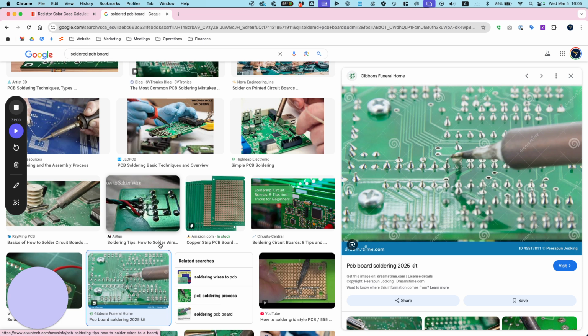Okay, that's good. Oh, I'm missing a little back there. You see that? Okay, so I'm going to just try to reflow it. Not even put any more solder. I'm just going to reflow it, just pressing it. Okay, it's not enough, so I'm going to add a little bit more here. Even though I tell you to use the third hand, I don't really use it a lot. I don't know how you can do it without it.